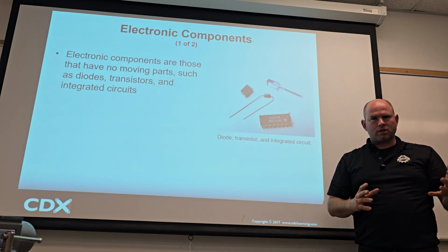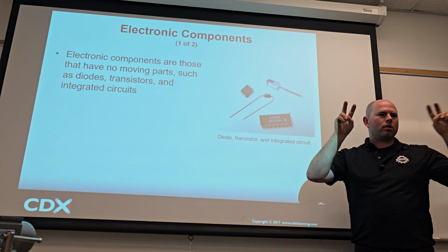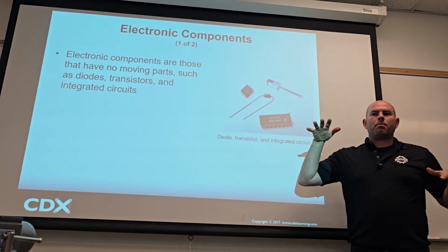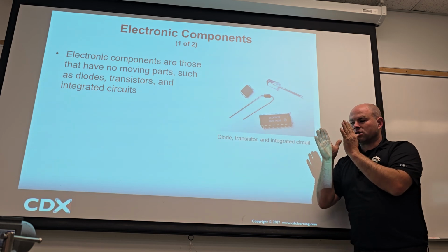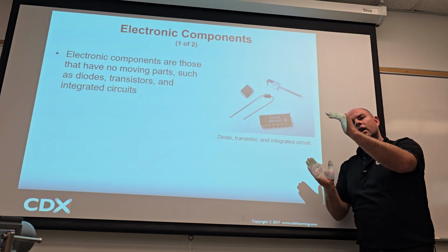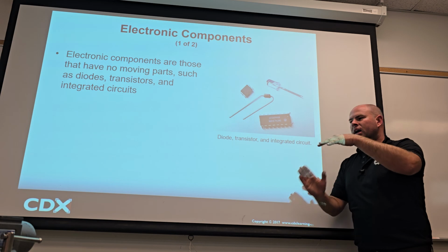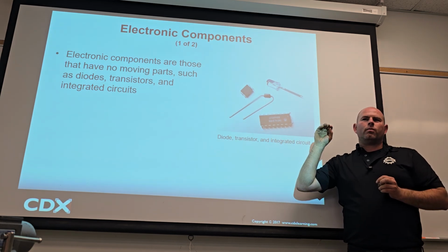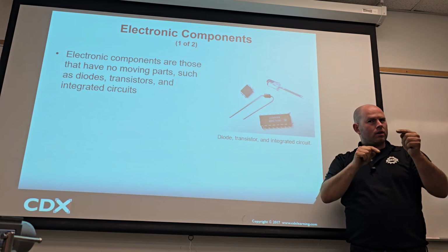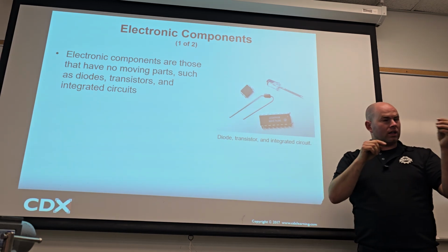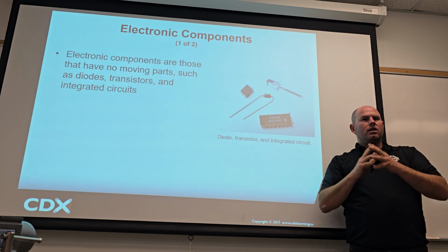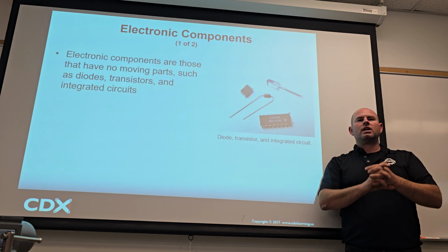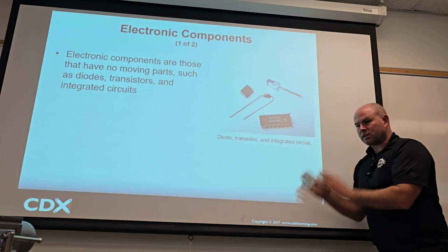The only thing really left in the circuit is the computer, right? But the computer can comprise a bunch of different things. It could be a printed circuit board that basically connects those wires to the end of the wire, cool? But it's going to connect those wires into a chip, into some sort of processing chip. Well, we don't really need to know if it's the circuit board or the processing chip or a broken solder joint. All we really need to know simply as the average common general technician is: is it the sensor?